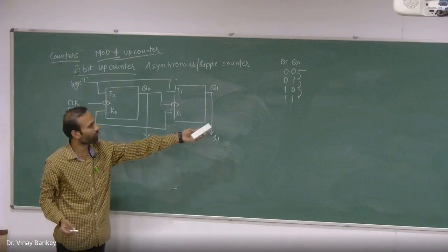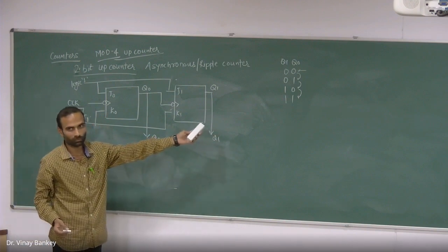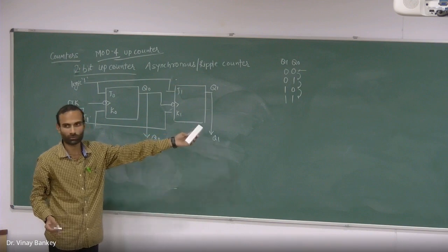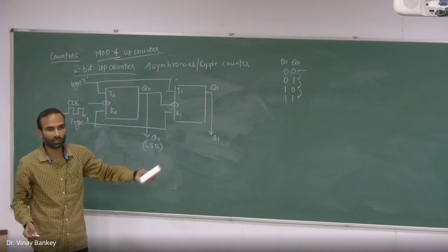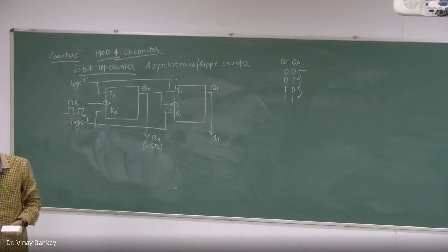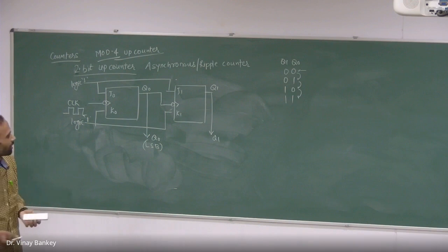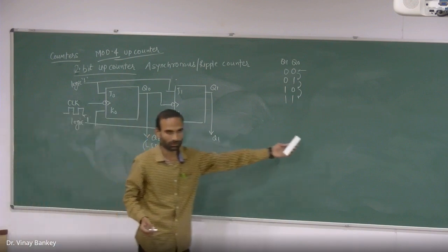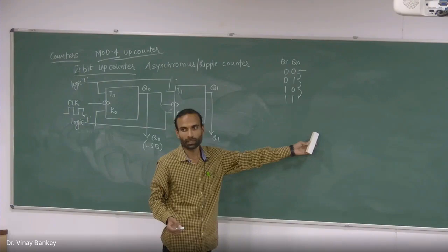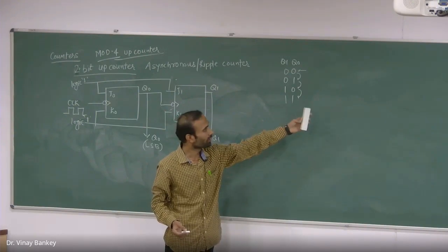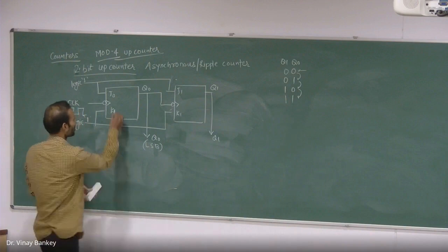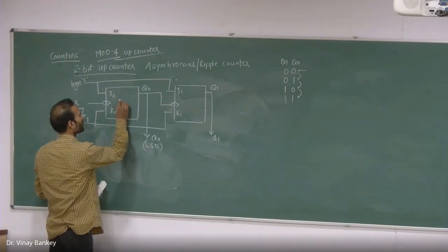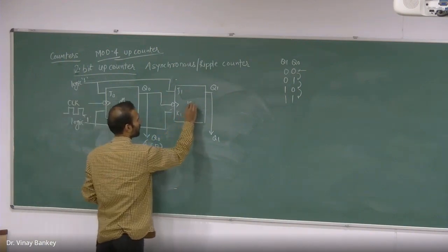Let's suppose we have 4 flip-flops here. So how many states will that counter count with 4 flip-flops? 2 raised to power 4, which is equal to 16. And the MSB bit will be associated with the last flip-flop. This is my first flip-flop, or the 0th flip-flop.